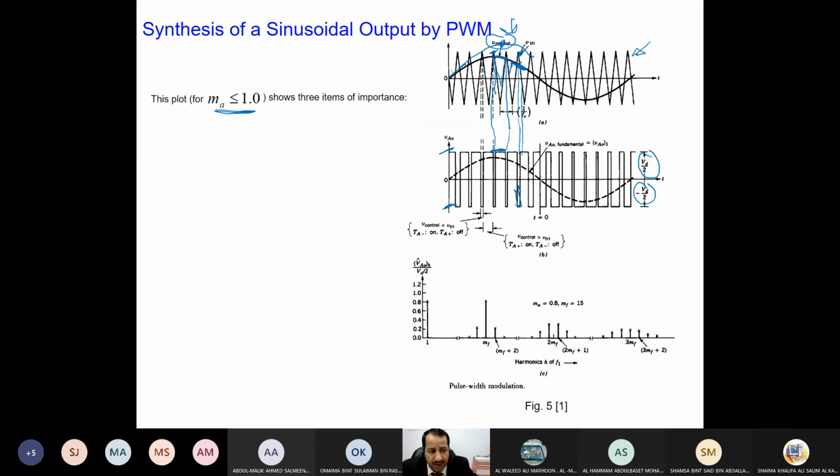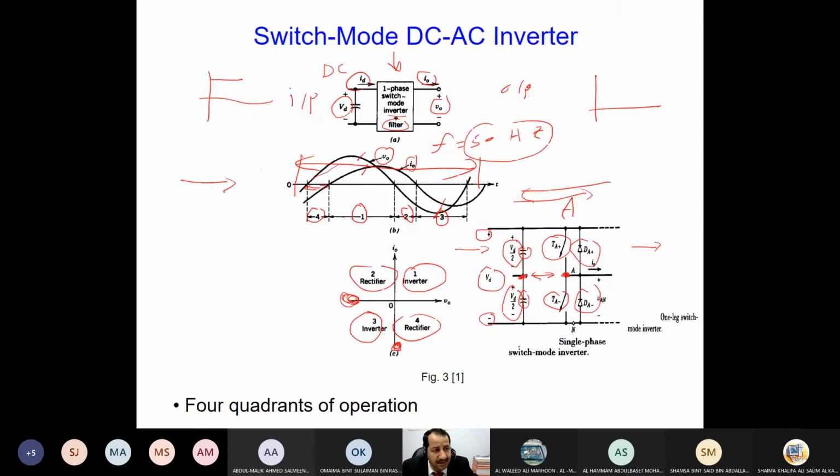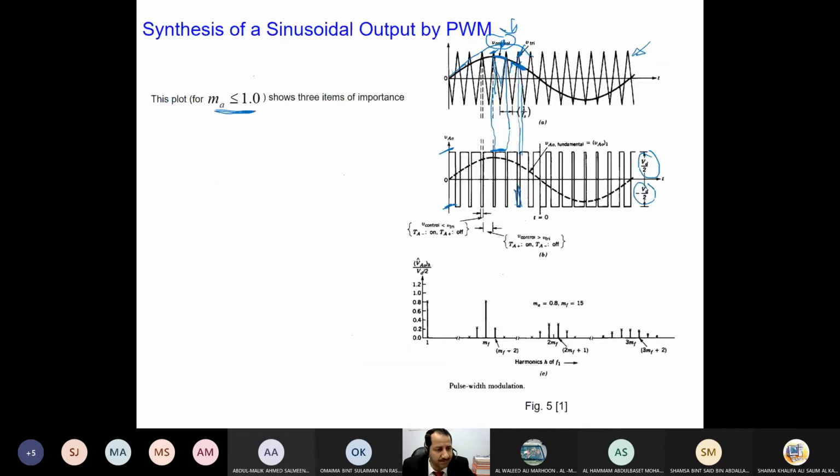Also, it is worth mentioning that we will have harmonics. Yes, I said this is what I'm looking for, to have a sinusoidal, to bend this DC in this way and make it sinusoidal. But it is not direct and easy. We will see that my waveform will be highly distorted and contain many harmonics. We will have some circuits as makeup circuits to smooth it, to modify it, to make it closer to sinusoidal, as I will explain.